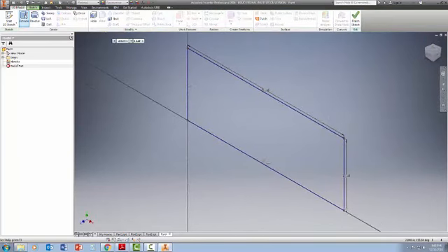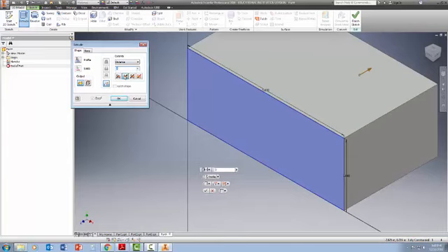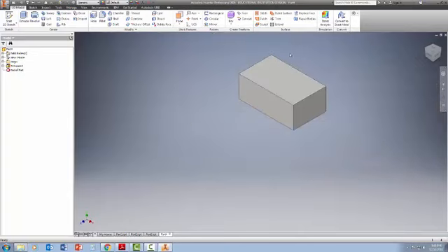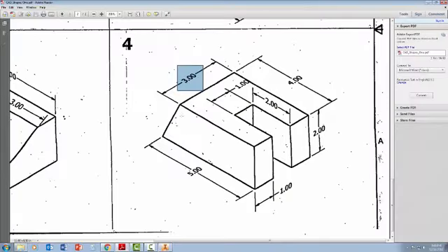I'm going to go to 3D model and extrude. And how far do we go back? We go 3 inches in direction 2. Alright, so I went 3 inches in direction 2. Click OK. Good to go. Now, let's take a look. I need to make a 4-inch line and then make a slant. Interesting. So let's start at this top right corner.